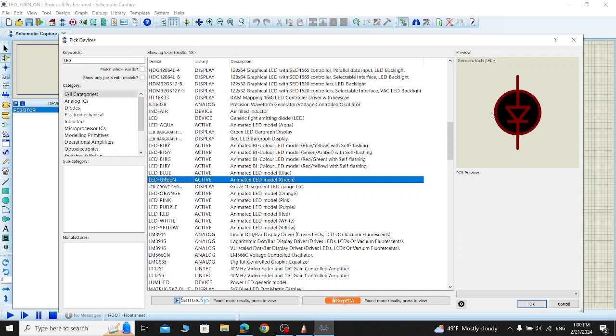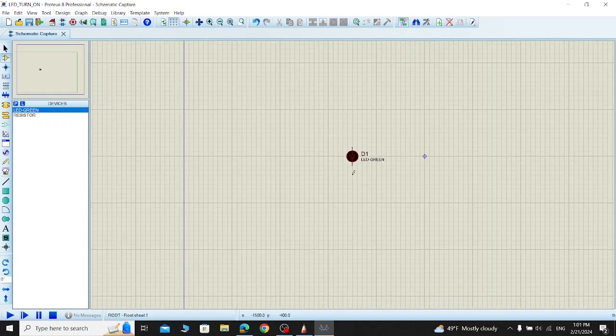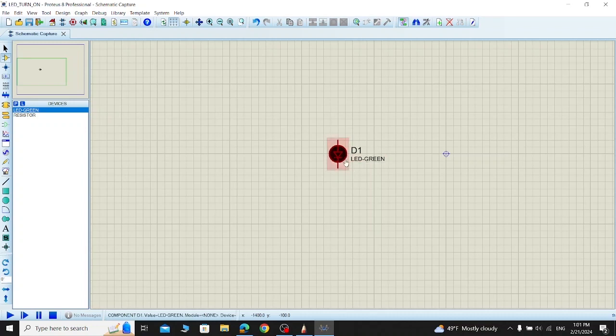We have the schematic model here. We'll double click here and then press OK. To place the component, we just need to select one of these and just click here. In this state, the component is not actually placed, but we can decide where to place it, and I'll put it here. Actually, the direction is very good, but if I want to rotate this, just click it and press plus, and you'll see that the orientation changed.